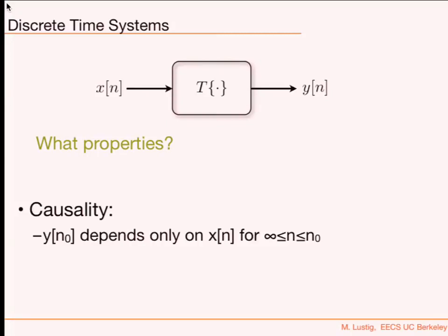What else? Time invariance, very useful. What does it mean, time invariance? Delaying the input gives the same effect as delaying the output. Right, a delay in the input gives you a corresponding delay in the output. That's right. That's a very important property. Because if we, for example, have a certain sensor, and let's say it's a temperature sensor, we'd like to see that if it's going to heat later in time, the sensor is going to show us the same heat, not something else. So it's a very important property.